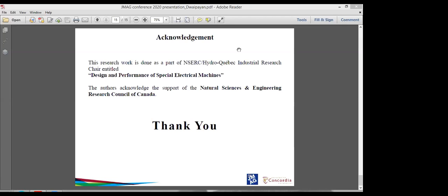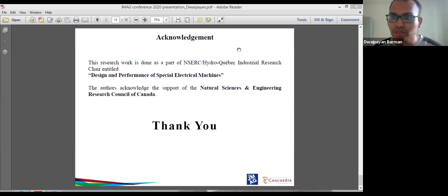Okay, first we analytically design the variable flux PMSM. Then those results are verified by using FEA. In my case, I use JMAG to obtain the flux linkage characteristics of the variable flux PMSM from 0 magnetization level to 100% magnetization level.